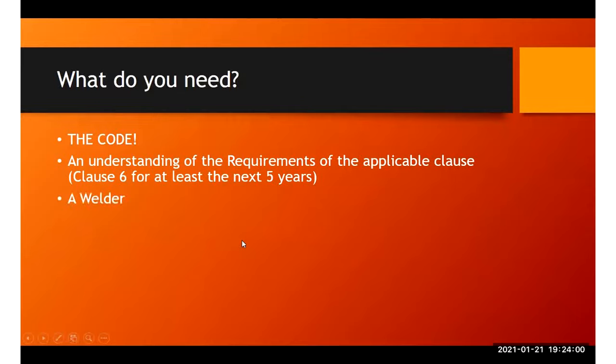You've got to have a welder. You've got to have a WPS that meets the requirements for the test. Okay, so one of the common misconceptions that I've seen in some industries is that a welder tests to use a WPS, and they don't. They test while they're using a WPS, and that WPS has to match the requirements for the test.